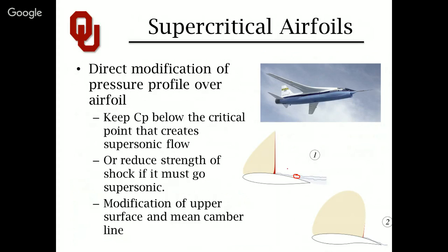The flow instantly goes back to subsonic, and the boundary layer itself separates. So you get a lot of what's called wave drag due to supersonic flow effects. Your engine is now losing energy directly to the flow surrounding the plane due to shock wave, and you're separating the flow behind it, making the situation even worse.